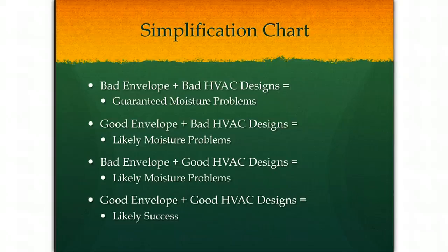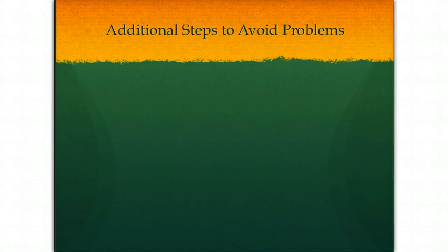Although new wall system products are often intended to provide better thermal insulation, reduce air movement through the walls, or allow enhanced drying of the wall assembly via vapor diffusion, they can also perform in unanticipated ways. These new products can dramatically change the way moisture flows through the wall and roof systems and the potential for condensation within these cavities.